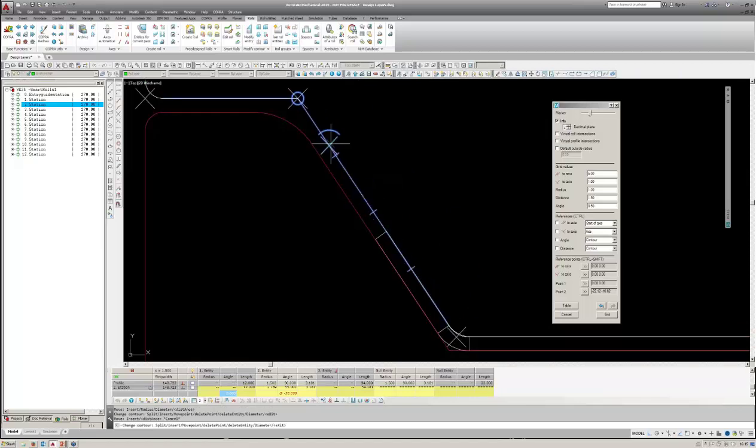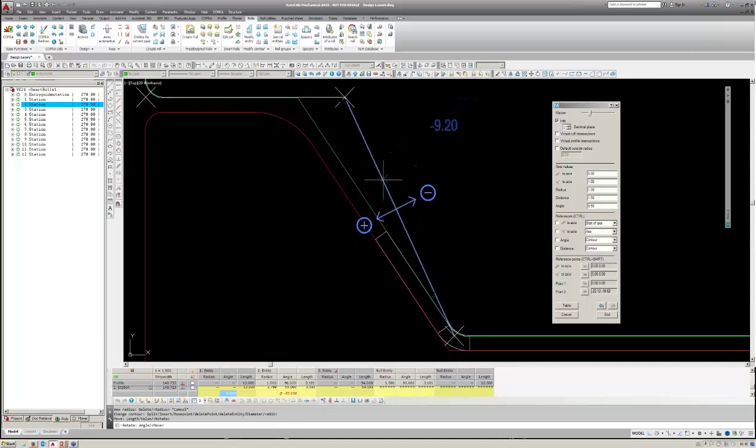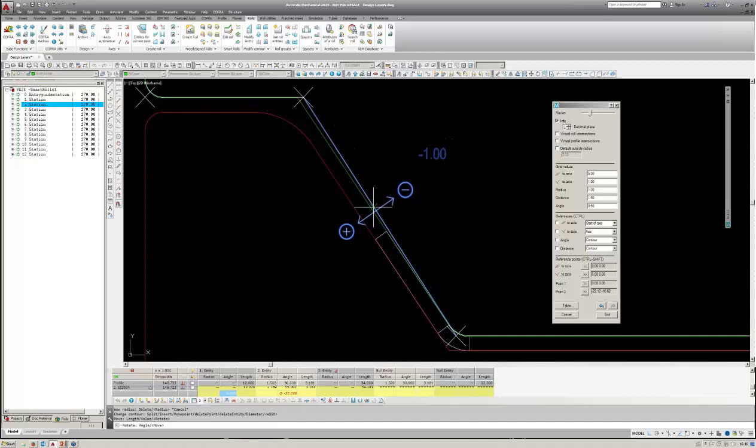If I go here to this position, I can pick here, sorry, wrong place, this position here between these two markers, and now I'm given the possibility to rotate. So I'm just going to right click here now to take me into the rotate command. You can see I can again freehand rotation here. And again, if I hold down the Control key, now snaps to 1 degree increments.